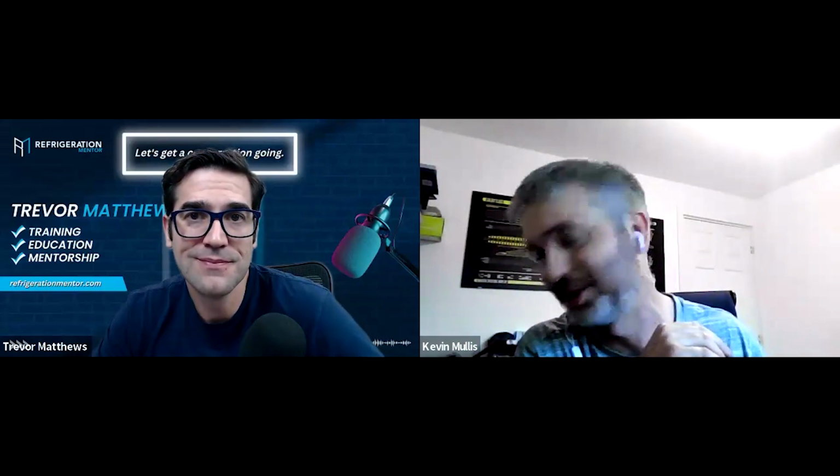My friend Connor, who works for one of our consultants in the UK, is a big believer in floating suction, and he is absolutely right that it works really well. It just has to be the right application for it. It's not suitable for every system. Your targets have got to be realistic. If you think you're going to get 0 degree shelf temperature out of 0 degree evaporating, you're not.